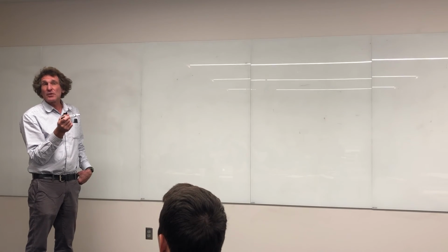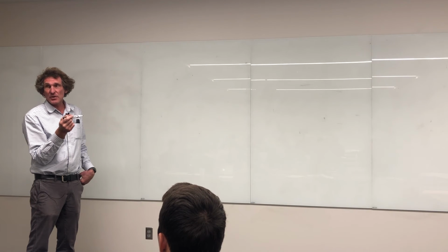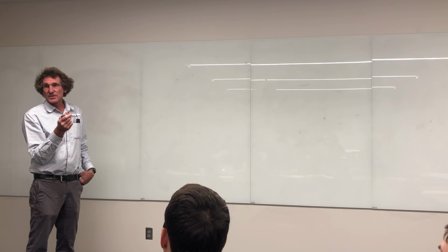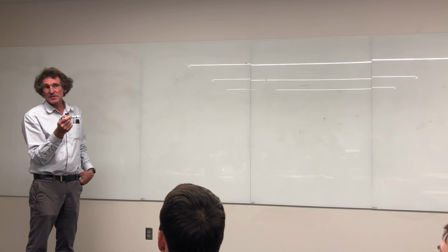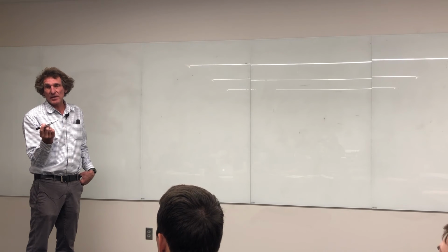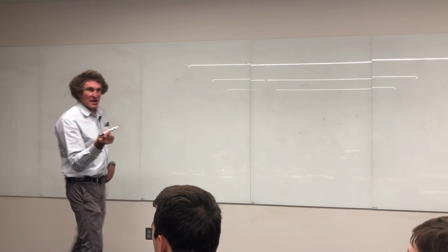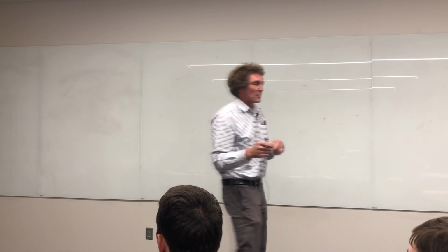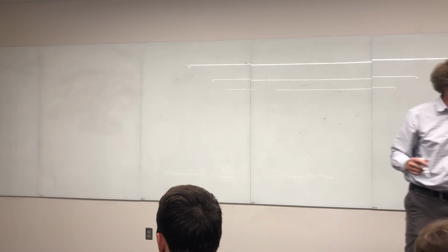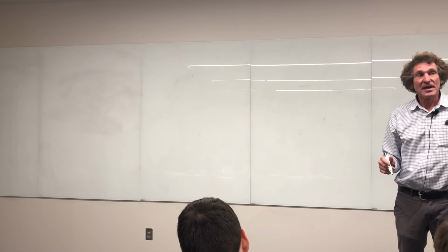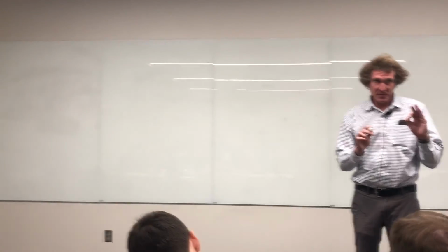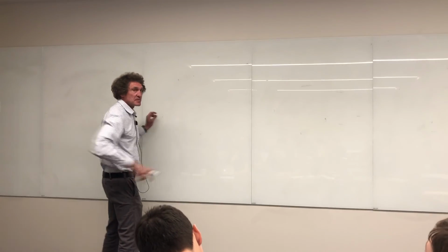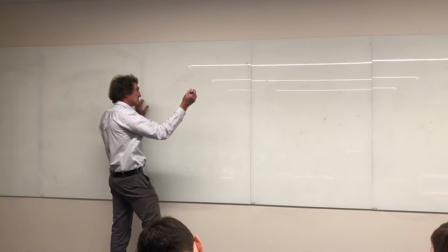Well, it's because I was at gigahertz frequency. This is 1.4 something gigahertz. If that would have been 50 or 60 megahertz, you wouldn't have noticed anything probably. So in high frequency engineering, it becomes important to be very precise with lead length and all that other stuff. But when you're doing high frequency analysis and engineering work, especially when you're doing port design, you have to start somewhere and get an idea. You build this and you see if it works. And the big thing is impedance matching. Hear me now. You want to impedance match the circuitry or everything goes sideways in a hurry. And also things blow up if it's a power amplifier. They will smoke.